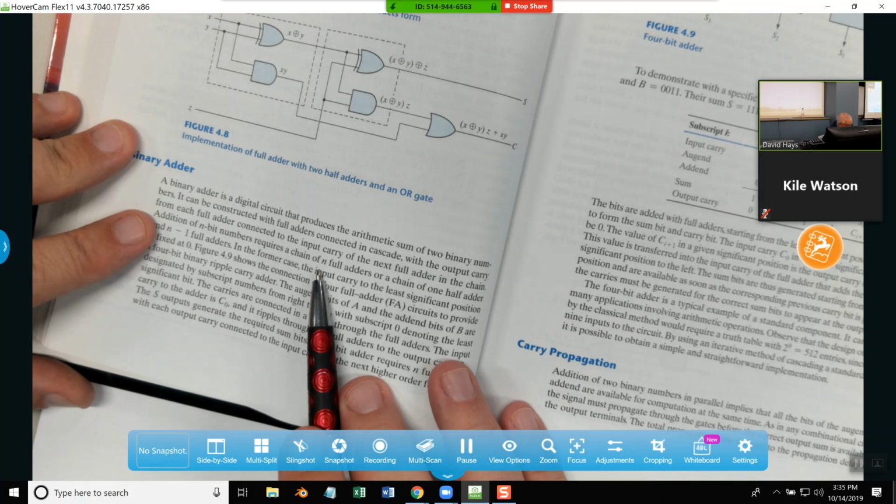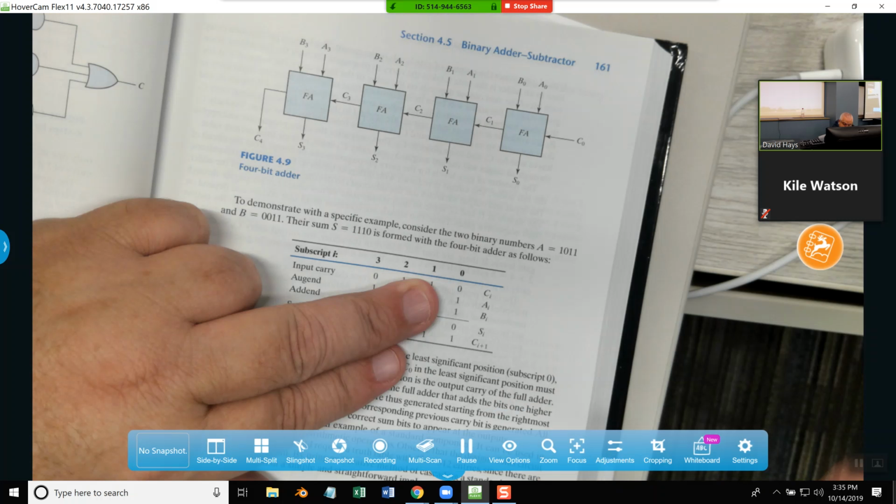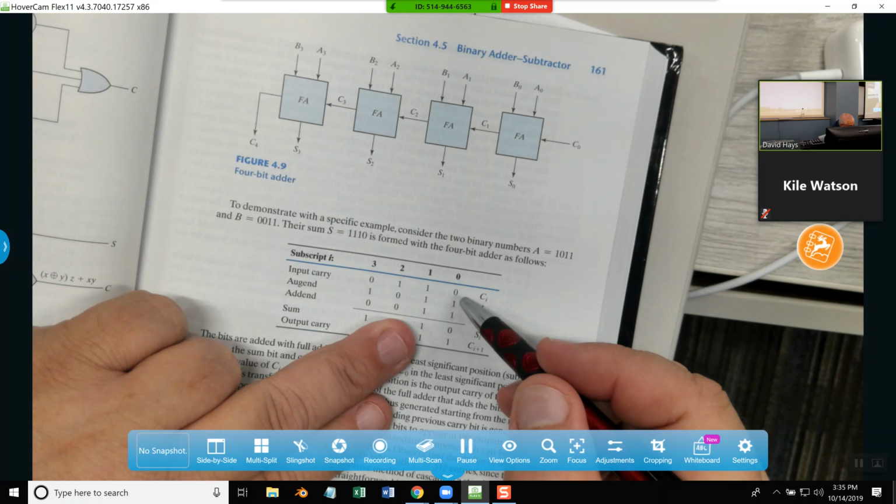Okay, 1 plus 1 is 0, and then I want to carry the 1. So this is giving me 0 coming down here, and then this is bringing a 1 over to here. So then here we're bringing this next two digits, 1 and 1. So this is 1, this is 1, our carry was 1. 1 plus 1 plus 1 is 3, so we'll have a 1 come out here, that's the S, which is right here, and then we'll have a carryover 1 coming over. There's our carryover.